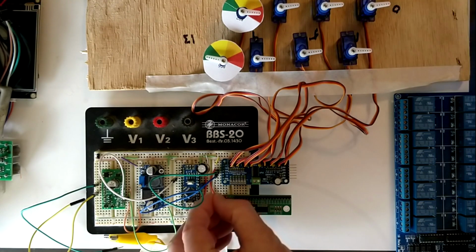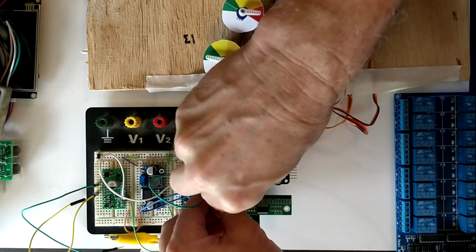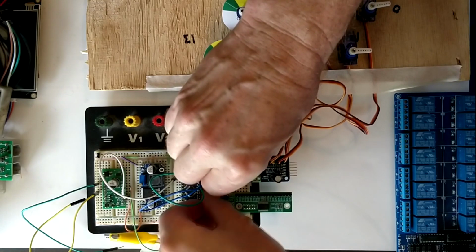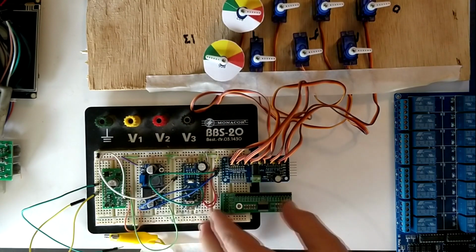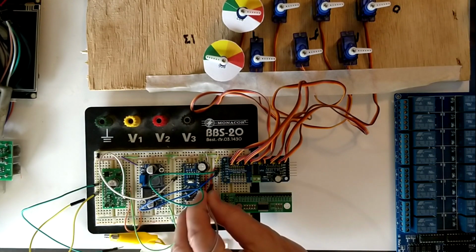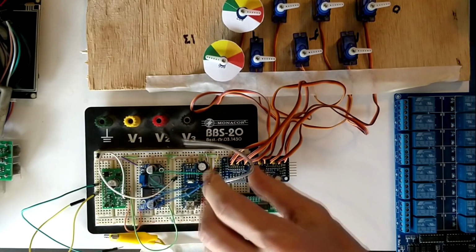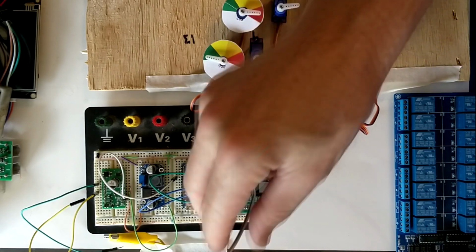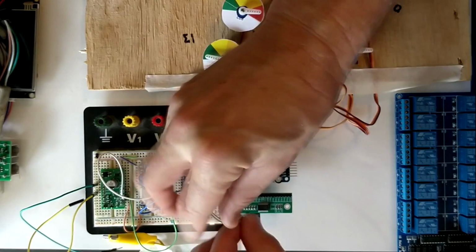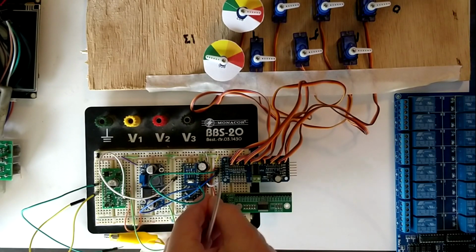The second thing we need to connect is the ground, and we can simply bridge from the PWM driver to the ground connection of the port expander. That's it. And then we need SCL and SDA, just as we had it before. So they are basically just connected in parallel. So the gray is going to be SDA and the white is SCL.